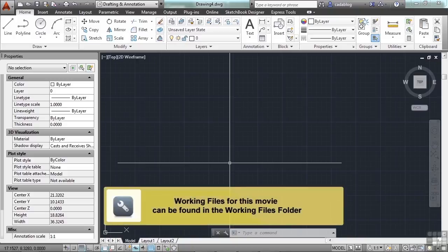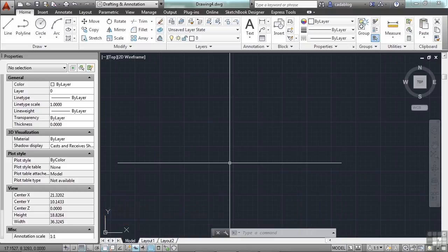Blocks are great tools that enable us to recreate similar line work rapidly. They can also contain metadata in what are called attributed blocks. A block attribute is a label or tag that essentially attaches data to your line work. Some examples of this data could be a part number, price for that part, specific comments, names, cost, manufacturer, anything